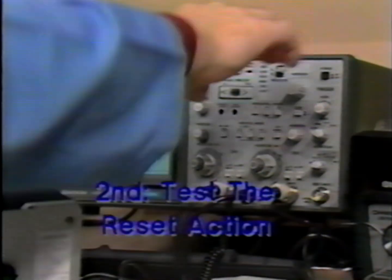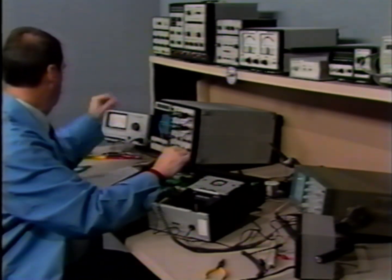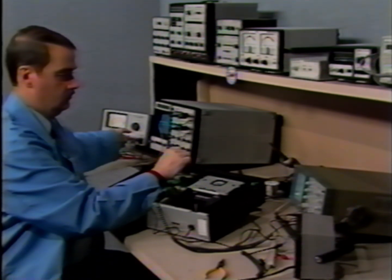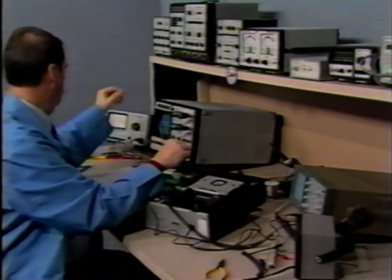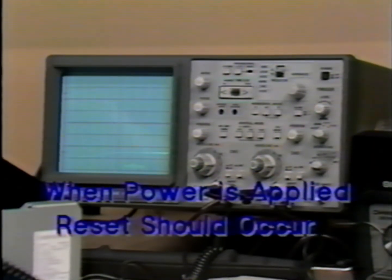To test the reset action of the line, an oscilloscope is connected to the reset input and the product is unplugged or turned off to remove power from the microprocessor. When power is applied to the product by either plugging it in or turning it on, the reset pulse should be seen on the oscilloscope.